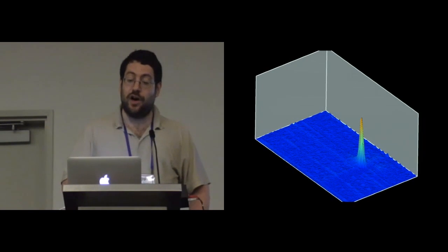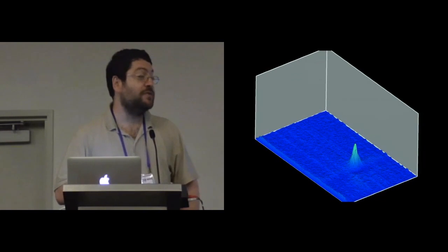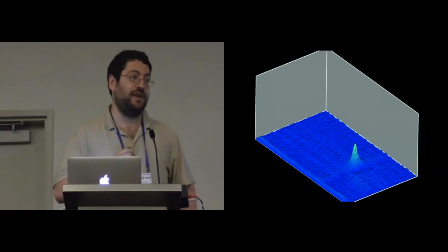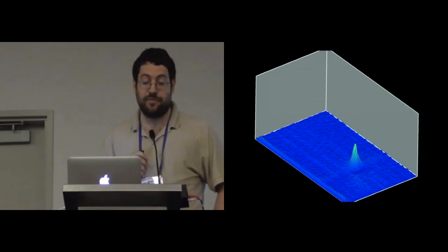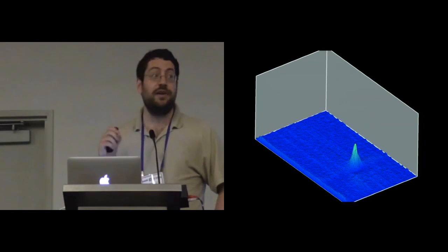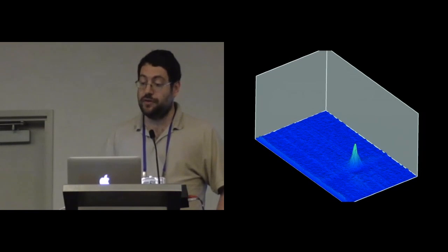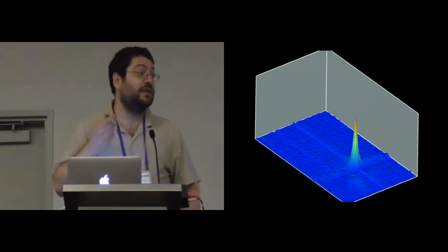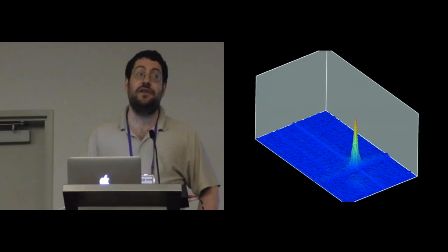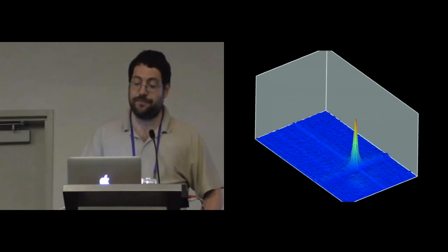So I'm going to take my finger off, and I'm going to put the measurement head onto the screen. Now the measurement head is not trying to create a touch right now. We still have a spike, and this shows just how sensitive the screens are in terms of picking up metal objects that are placed onto them. But it's a low enough spike that it doesn't trigger a touch event. If I now go and turn the relay on, we get this, which is a spike that looks exactly like a finger. So as far as the screen is concerned, the measurement head is identical to a human touching it.